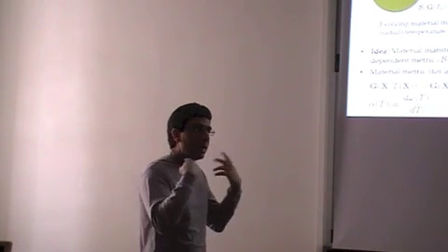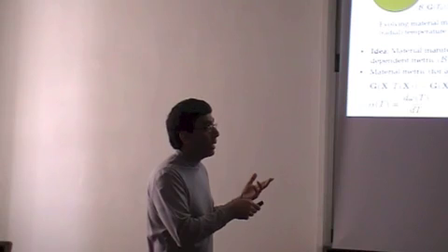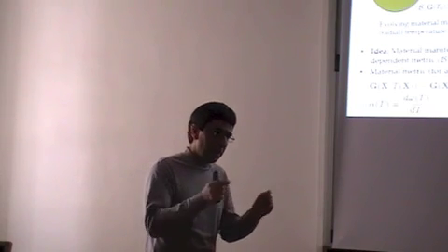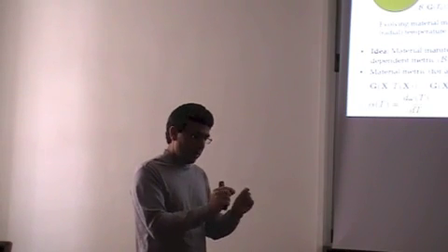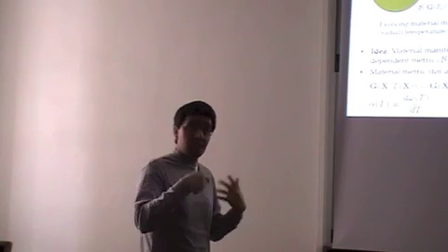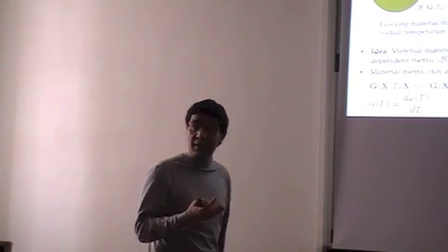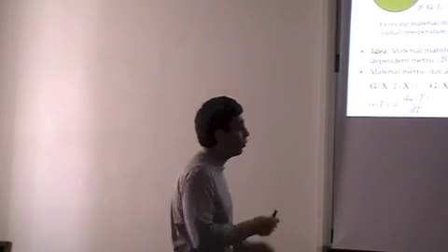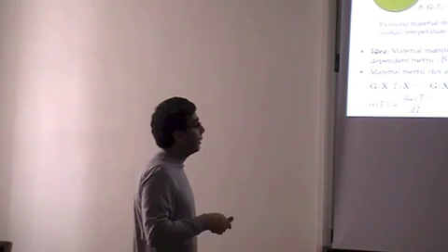But now let me imagine I put this body in a Riemannian manifold with a metric that explicitly depends on temperature the right way. Meaning that when I look at this underlying set here, the distance that I measure is really this, which is the natural distance that this temperature change is dictating. So in that Riemannian manifold, I'm stress-free by construction. So my problem is really now a classical nonlinear elasticity problem.